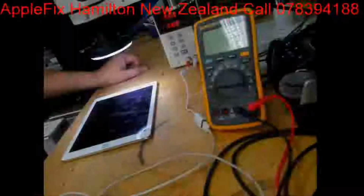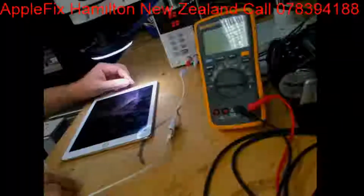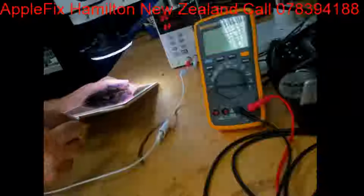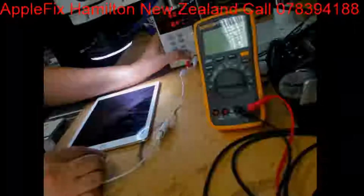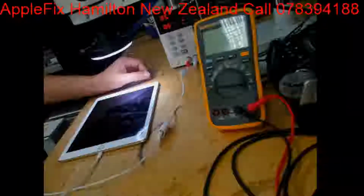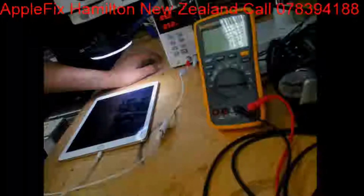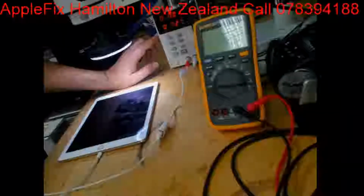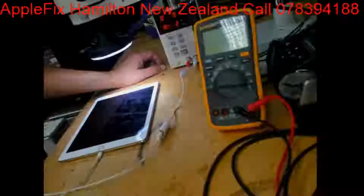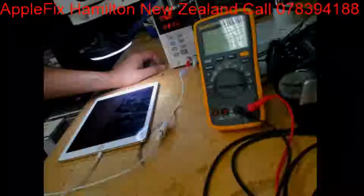I will show you here. It's connected to the DC power supply, so I'll put it here and give it some power, turn it on, and then you see here that it's drawing 0.5, half an ampere, and then dropped again and goes back to zero. So this iPad is not shorted, so there is something wrong with the power lines.